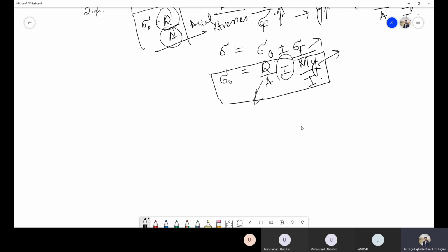And there is another type of stress, that is shear stress, for which the formula is this one. So can you tell me what is Q in this formula? Anyone? Sir, applied load. What is V? Shear. V is the shear force. Yes. Actually, sir, this Q is slightly different than the applied load. You may have to revise your notes.